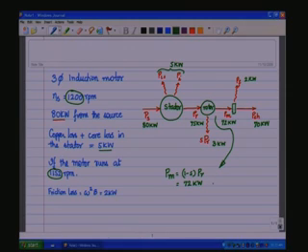Now that is equal to the torque that is generated by the motor, let me call that one as TG, into omega M. Or on the other hand, if we want to find the torque which is independent of omega M, you could use this equation also. But anyway, we have this, and therefore TG is equal to PM by omega M.